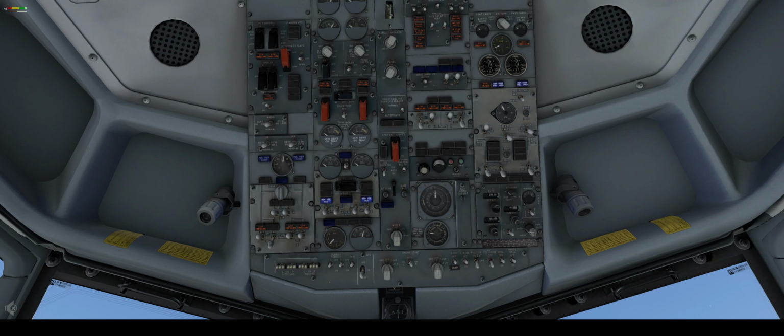And what else to say regarding limitations? For example, in the last company I flew, we got 400s. Okay, and the limitations were for example, maximum oil temperature was 165 on the engine.